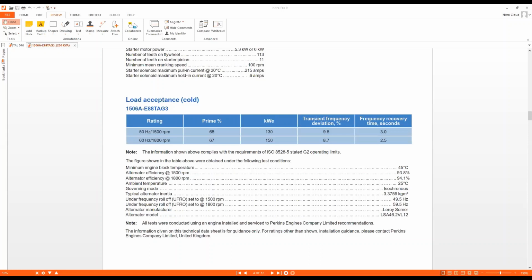I should really stress on this point. It differs from one engine to another. But ISO 8528 allows for 5 steps, okay? So when we talk about these deviations or transient responses, yes, it's as per step load. Muzammil is asking, so it means we cannot load single step 100%? Not at all. It's totally not advisable.